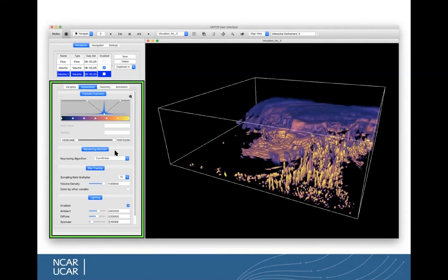There's also other parameters in the appearance tab depending on the renderer you're using. Like for our raycasting renderers, like the ISO surface and volume renderer, there's lighting parameters, different algorithms you can pick, but the transfer function is the big one that's common amongst all renderers. Every single renderer is going to have a transfer function in its appearance tab that will behave in the same way. So once I show you guys how to use a volume renderer, hopefully it'll be apparent how to use all the other renderers and apply color because it all works in the same kind of way.